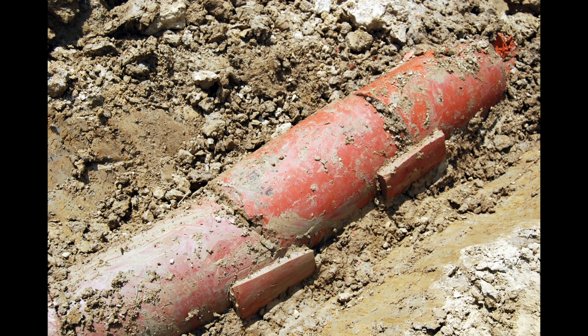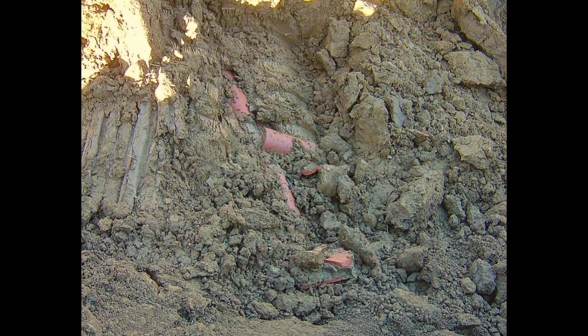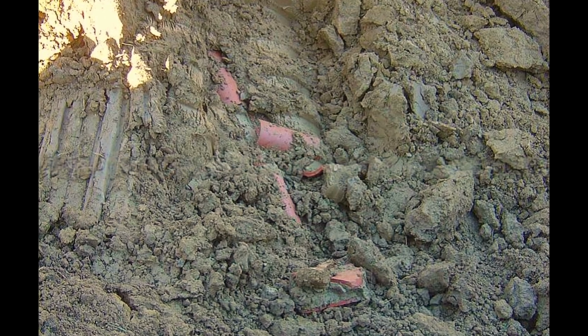Some of the clay drain tiles had unique patches on them, and these were designed to block any wide gap between the drain tiles. Digging the core trench and building the groundwater dam ensured that buried drainage structures were found and disabled. Some of the clay drain tiles were broken and plugged, like what you see here. These may have been laid on a foundation that was too soft, and as they were being covered with soil, they could have settled into the ground.